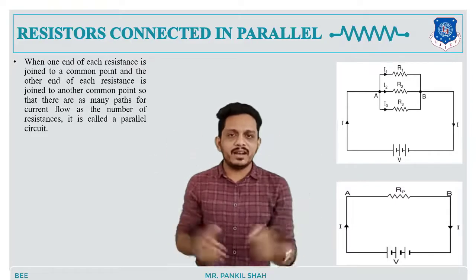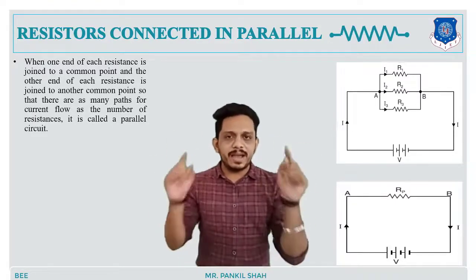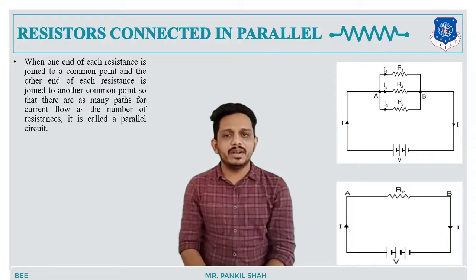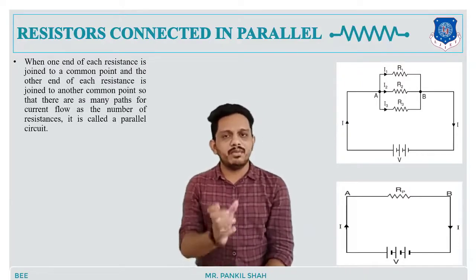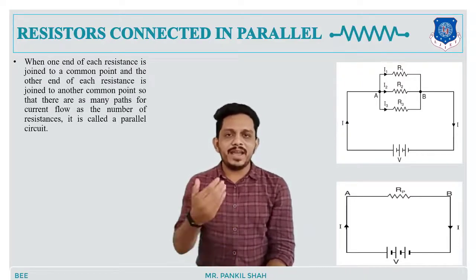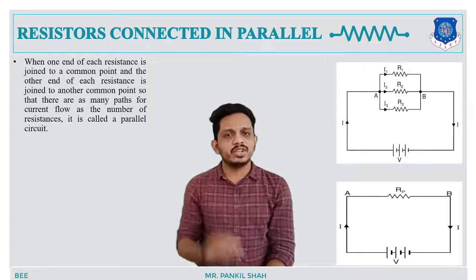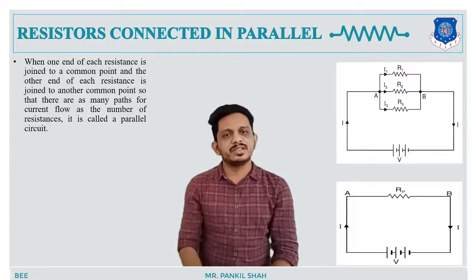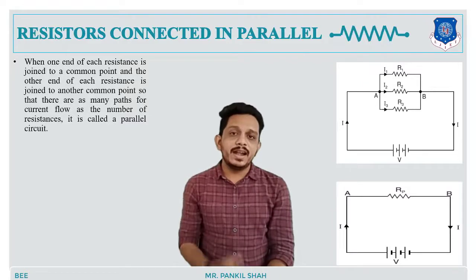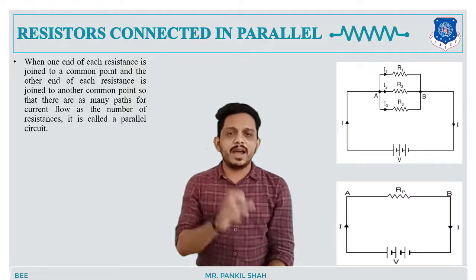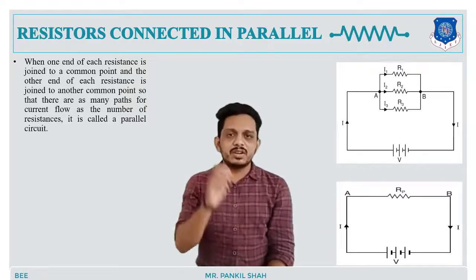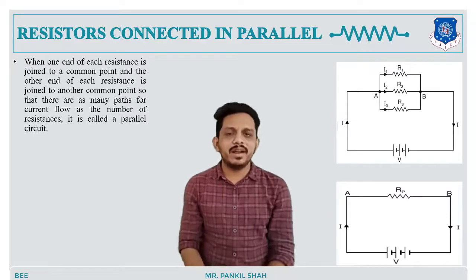You can see this parallel connection in this figure. This parallel connection is supplied by the same DC voltage source, a battery of V volt. By applying this V volt to this combination, I is the current flowing through the circuit. But you can see in this figure, now the voltage applied to each resistor will be the same, because it is a parallel connection.